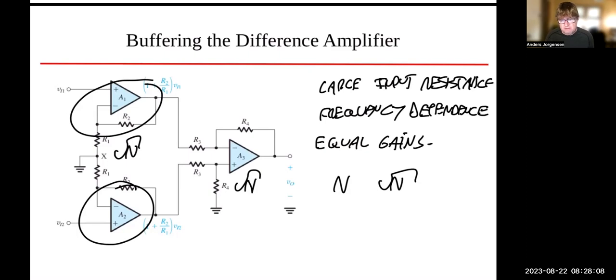and I have a bias of, let's say 5 volts, the first stage is going to take that 5 volts and amplify it by a factor of 10 to 50 volts. And if my op amps are powered by plus and minus 15 volts, they're not going to be able to produce 50 volts.